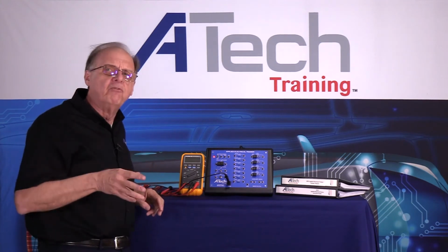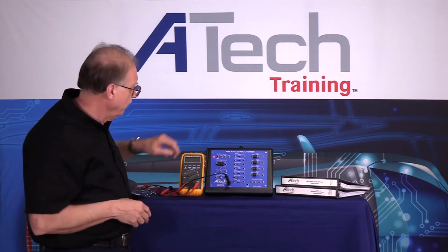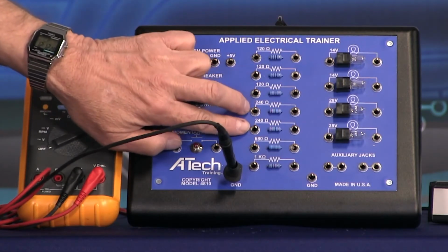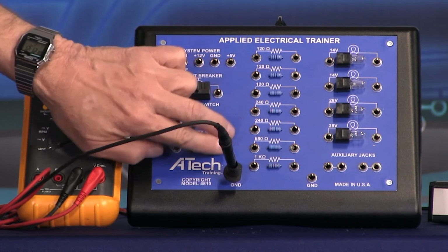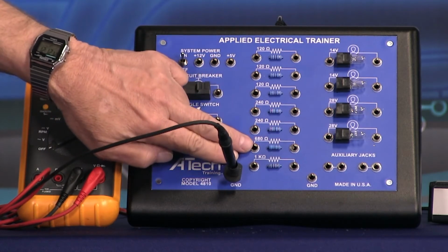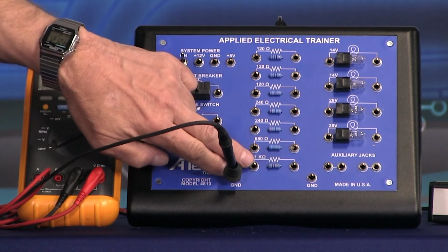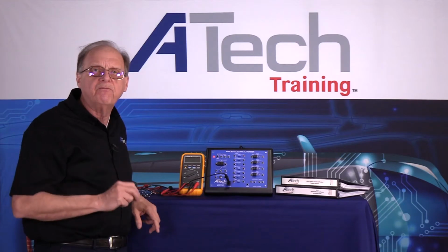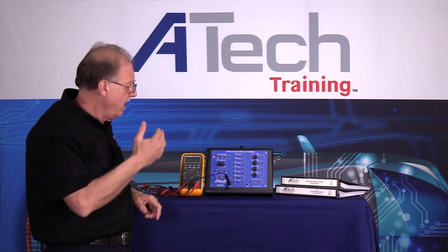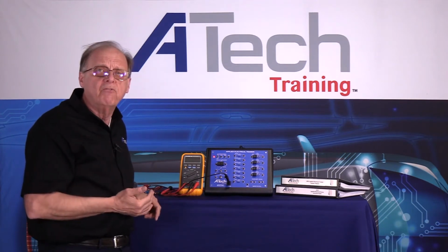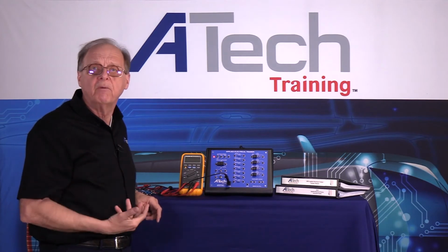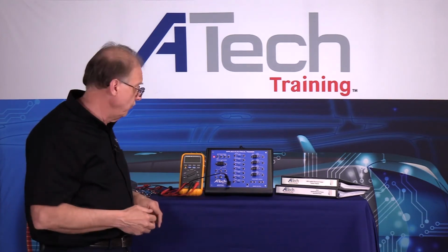But it also allows you to build a variety of circuits. So I have three 120 ohm resistors, two 240 ohm resistors, one 680 ohm resistor, and one 1 kilo ohm resistor. That's in the center. These resistors are in there for safety and limiting. The other thing is that having even readings on this is going to make the math a lot easier. It's going to make it easier for them to calculate Ohm's law when they're using it.